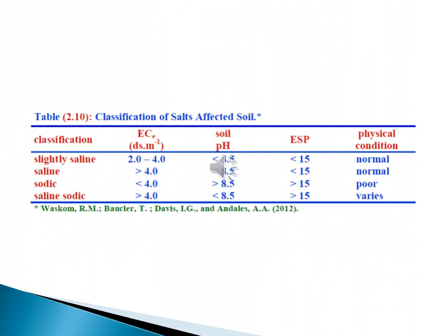Table on classification of salt-affected soils: electrical conductivity of soil paste, soil pH, exchangeable sodium percent, and physical conditions for slightly saline, saline, sodic, and saline sodic soils.